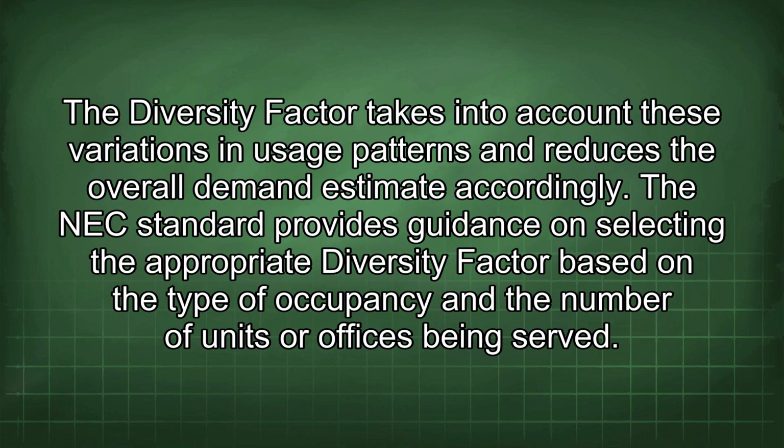The diversity factor takes into account these variations in usage patterns and reduces the overall demand estimate accordingly. The NEC standard provides guidance on selecting the appropriate diversity factor based on the type of occupancy and the number of units or offices being served.